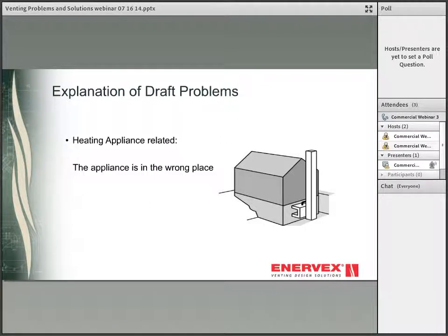You can also remedy it to increase frontal velocity, including the following: increase the chimney height using the same flue area, and extend the last tile 6 inches or more upward. You can decrease the frontal opening by lowering the lintel or raising the hearth. And you can increase the free area through the damper. Ensure that it is fully open and without interference. And last, the ultimate solution is to install a mechanical draft system.